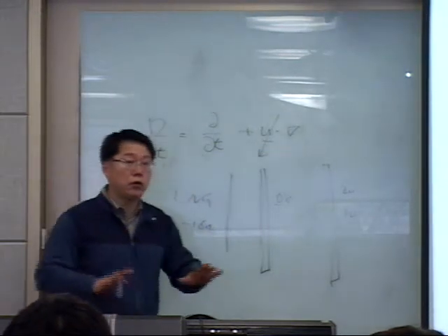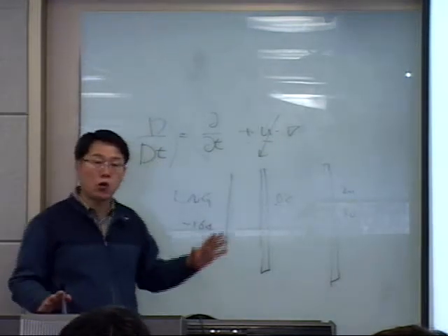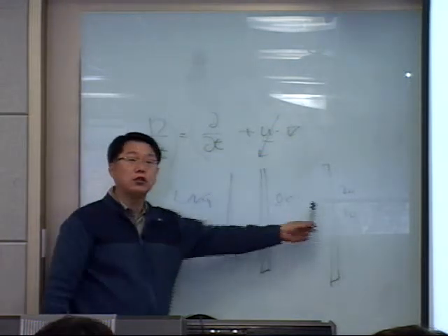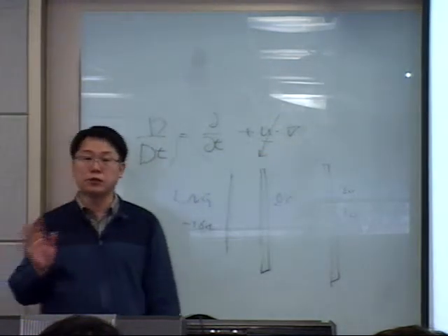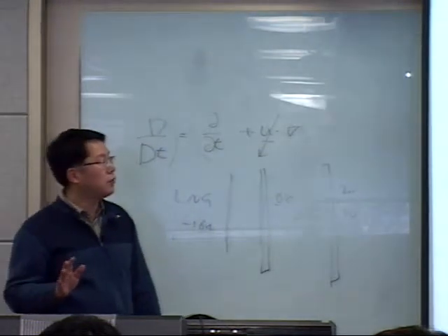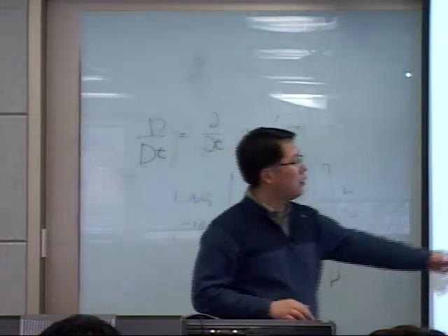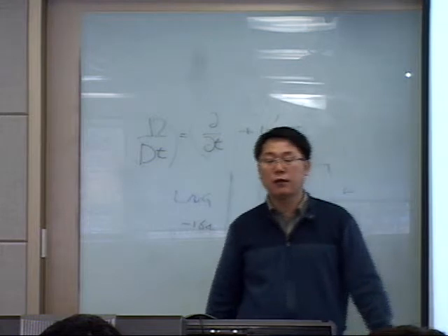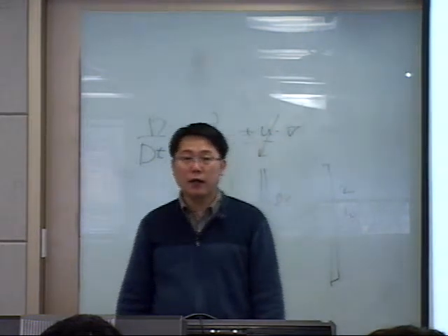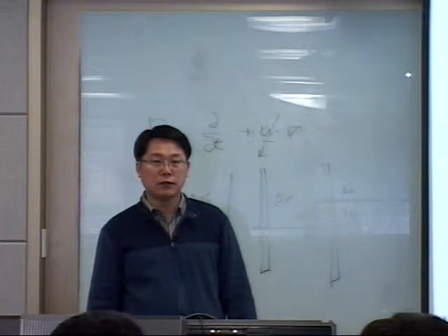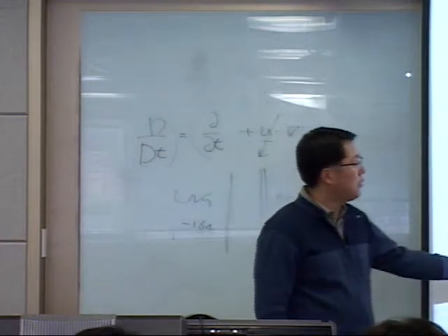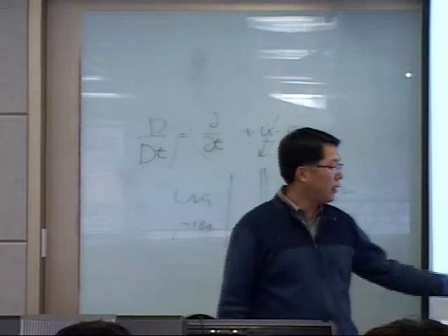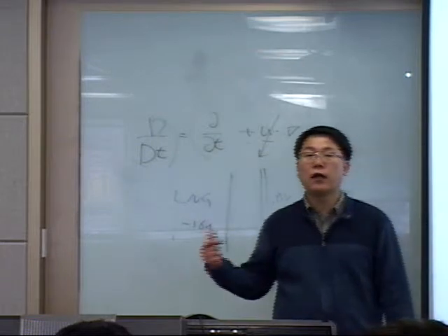So if you have a structural analysis code, you can generate a mesh and impose some boundary conditions, then you can have the temperature distribution. If you have the temperature distribution, the heat flux is given by this equation: minus thermal conductivity k times the temperature gradient. If you integrate this heat flux over the whole area, you can get the total heat ingress.